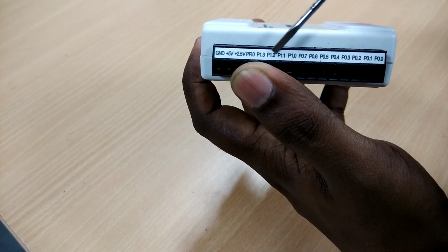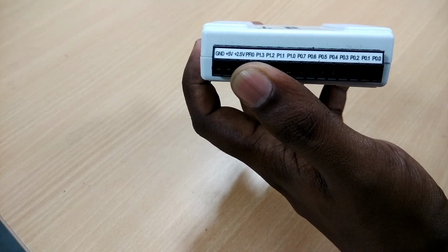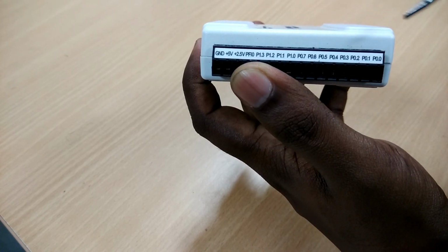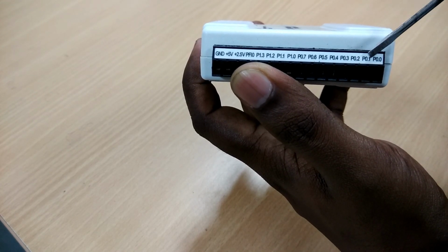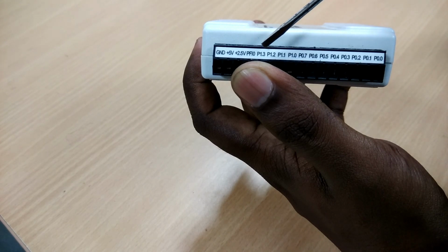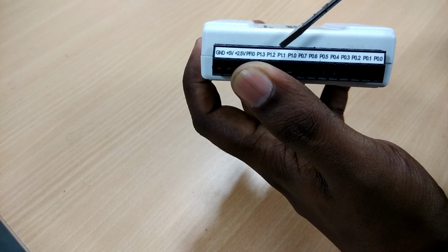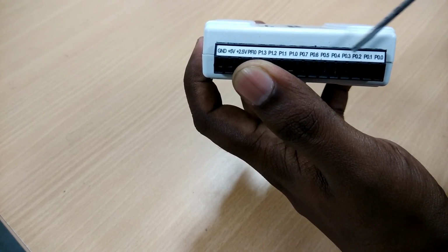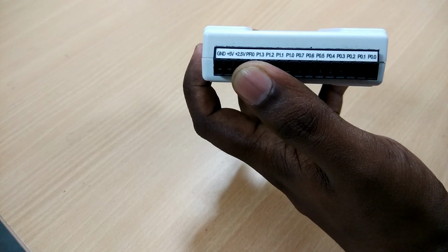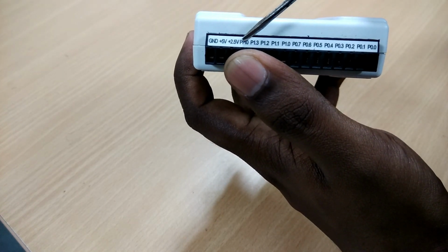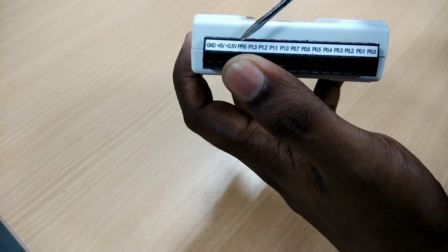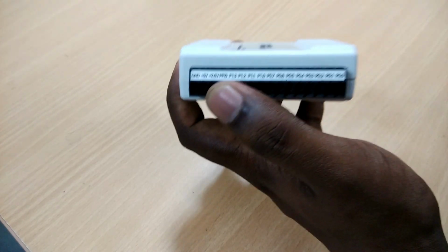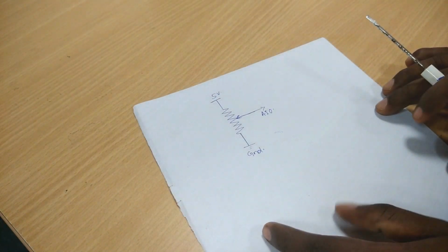These 12 channels are clubbed in 2 ports, that is port 0 and port 1. Port 0 has 8 I/O lines and they have been labeled as P0.0 to P0.7, and port 1 has 4 lines labeled as P1.0 to P1.3. The maximum voltage level of digital signal the DAQ can handle and generate is 5 volt. There is also one PFI0 slot which is used for specific purpose, either for digital trigger input or event counter input. I will discuss about this in my future video.